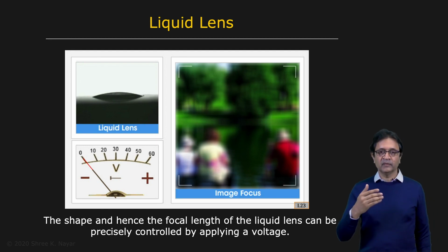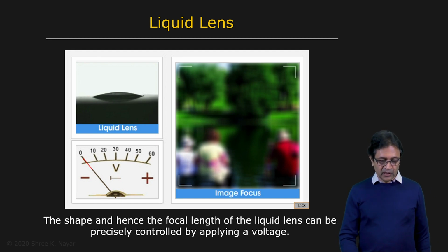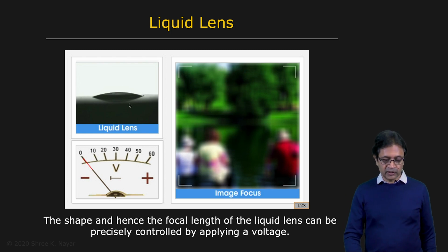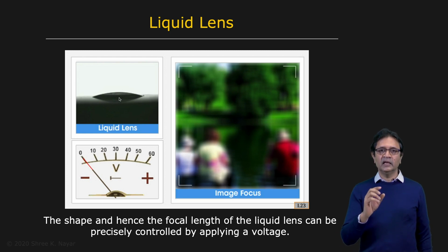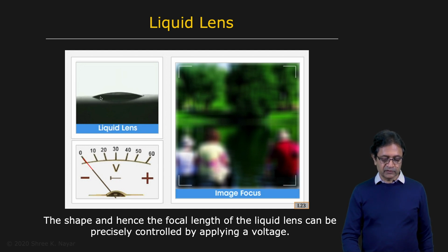Well, recently, people have been working on liquid lenses as well. So this is a liquid lens by a company called Myopia, which was acquired by Corning. What you're seeing here is a process called electrowetting. If you apply an electric field to this liquid, it changes the curvature of its surface. So here is the lens. Here's an image seen through this liquid lens, and here I'm showing you the electric field that's being applied.